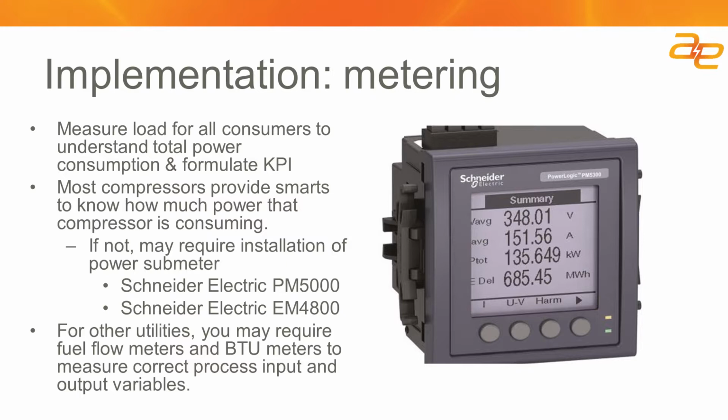It may be measuring pressure at the end of the line. If you are trying to maintain a set point for your compressed air, you may need to measure the pressure at the furthest point within your system.